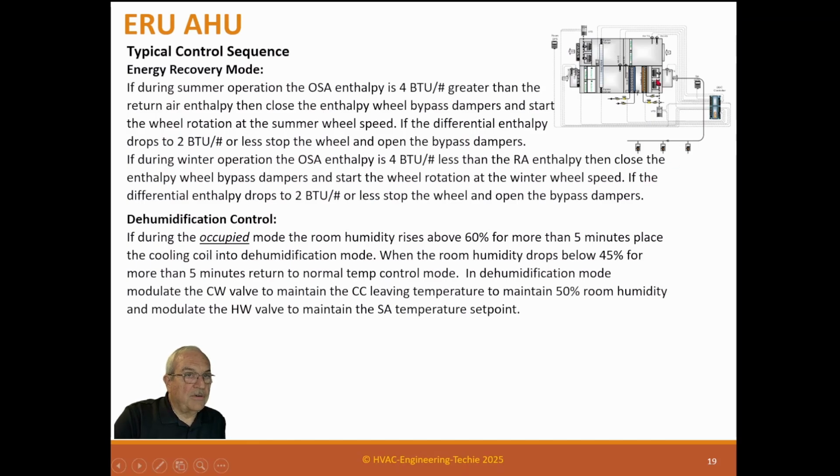Now remember, this air handler has a heating coil downstream of the cooling coil, so we can actually do dehumidification. If not, then we would be putting very cold air down to these air handling units. And during dehumidification mode, that may be okay, but it may not. So basically, you're going to reset it now. You could reset less than you normally would if you were going down into a space, but you still have to reheat, so a reheat coil is required.